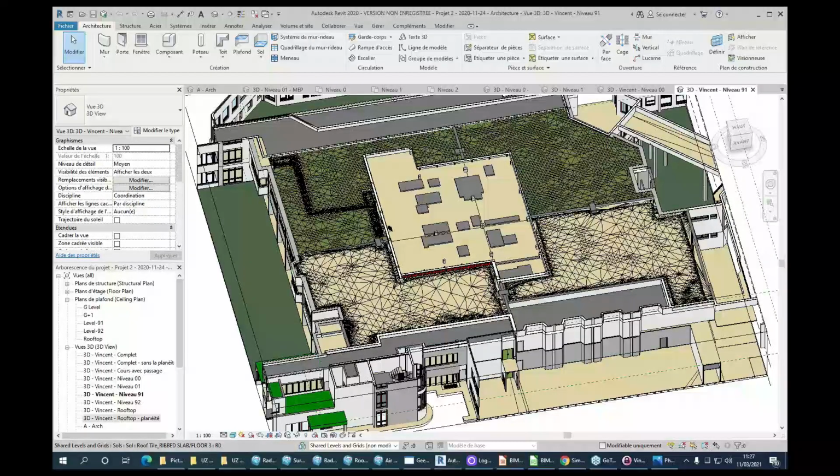Well, not really, no. The goal is to have an accurate reading. We know that point clouds are not going to match exactly. There's always a very slight discrepancy. If I take the example of the house that we had just before, the typical mean error between two point clouds is less than 2 millimeters, which is really good. So practically, it's not much of an issue. We did not notice that. It's within the accuracy of the scanner.